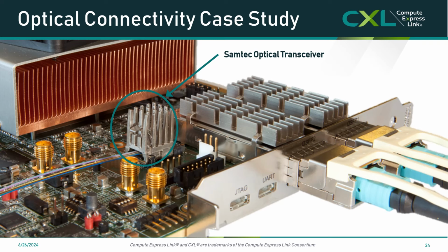We talked about the density that Firefly offers in terms of its small form factor. Here we show in the circle just one of our x4 Firefly transceivers next to 2 QSFP-DD form factor MSAs. So we see about a 4-to-1 space savings on the PCB using a midboard optical transceiver versus front panel pluggable. Again, we're not trying to say that the midboard optics works in every application. It doesn't. But for applications where density, signal integrity, CXL operability is there.